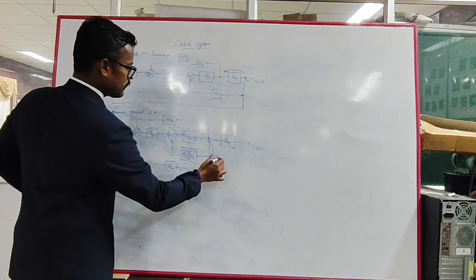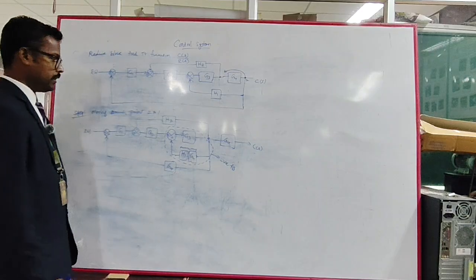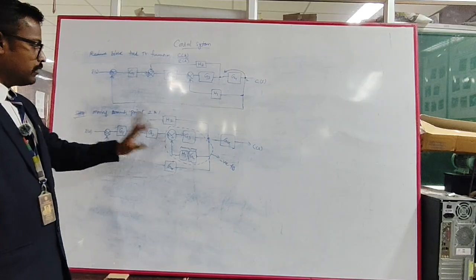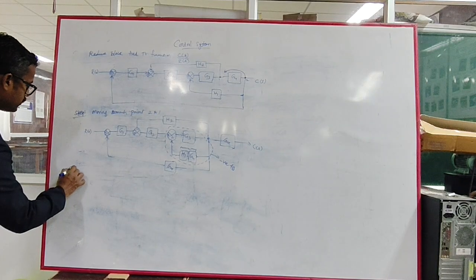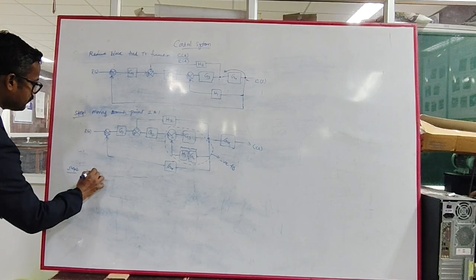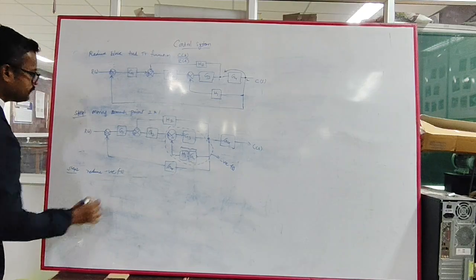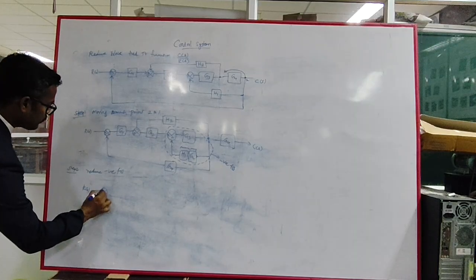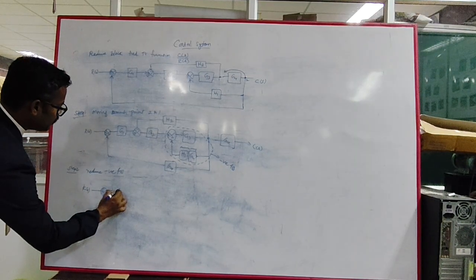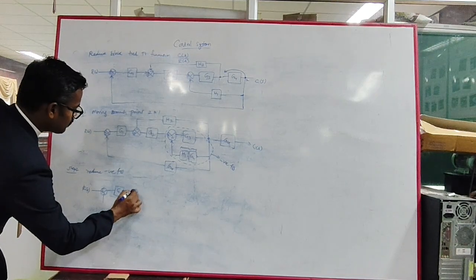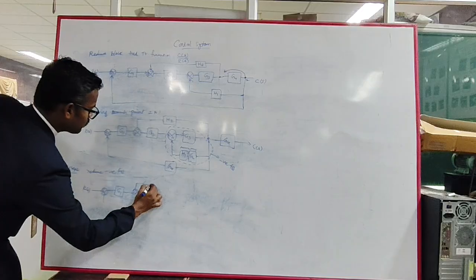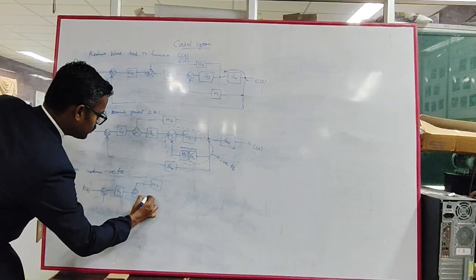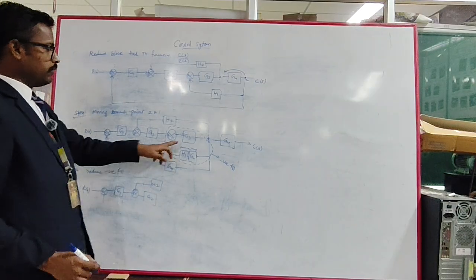Okay, this is a negative feedback loop. Okay, so is anything else able to be simplified in this step? Nothing. Okay, we are reducing the negative feedback. Okay, the step 2 is, so reduce negative feedback. Okay, so you redraw these things, plus minus, and this is G1, H2, and this only simplified. Okay, this is G2. Okay, this negative feedback is simplified.